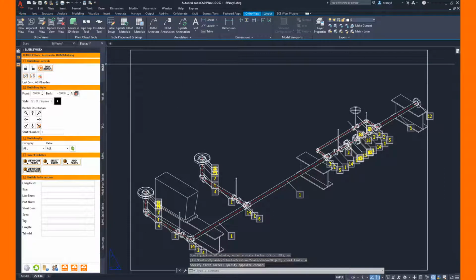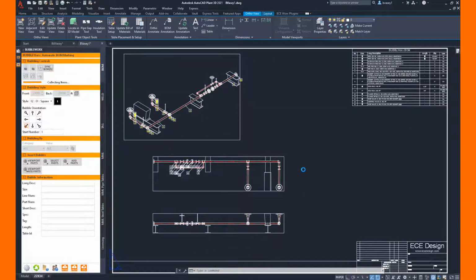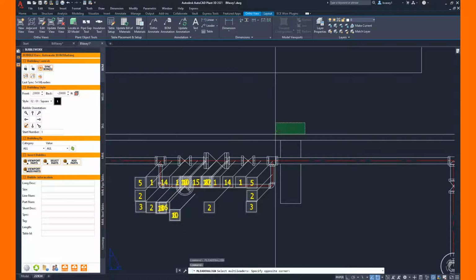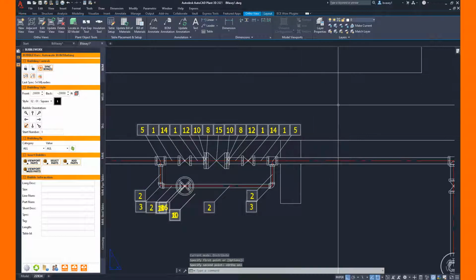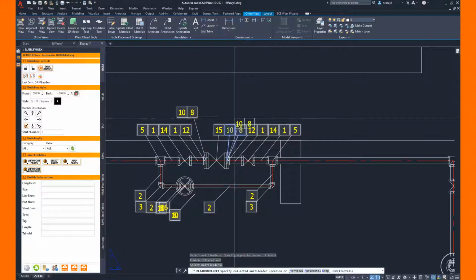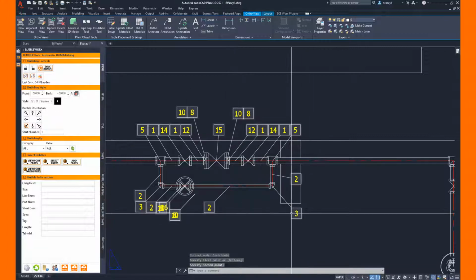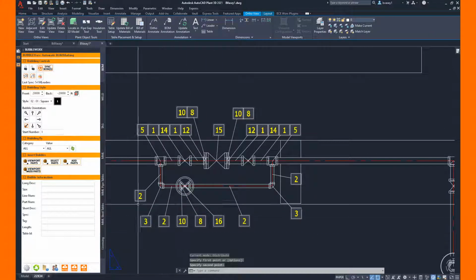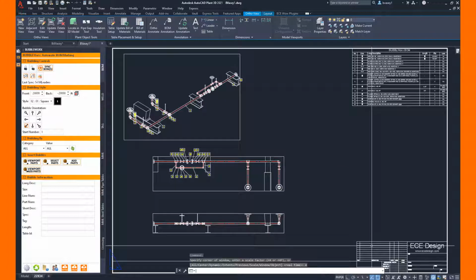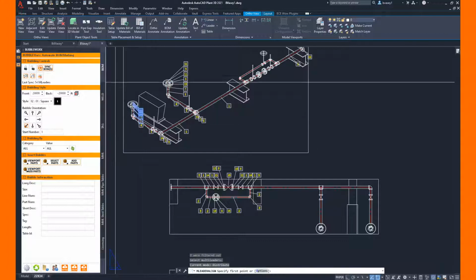I'm going to look at this viewport in particular, and here I see a dense concentration of bubbles around that bypass. I can go ahead and remove those bubbles from that view and just very quickly add them to another view. So at this point we have some bubble cleanup, and just using the BUBBLWorx utilities that are fundamentally AutoCAD commands, we can go ahead and do things like combine bubbles into one bubble coming off a leader. But just with a few clicks of the mouse we can move bubbles around and satisfy the orientation such that they're spaced well enough apart for accessing hyperlinks once we transition this to a PDF.